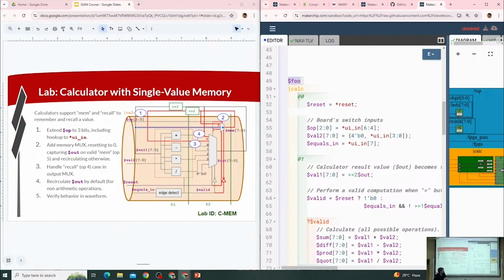Meaning inside the pipeline or outside the pipeline? If it's connected up to other logic, if I needed to refer to it here and it's outside the pipeline, I would have to reach outside the pipeline to grab it. And reaching outside the pipeline, I actually have to give it an explicit reference. So since I'm in stage 0, this is also assigned in stage 0. This would be a direct hookup to this foo. If I move it inside the pipeline, of course, I don't need this part.